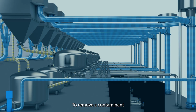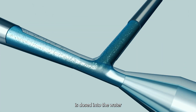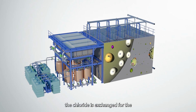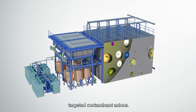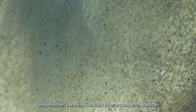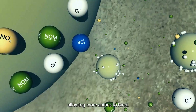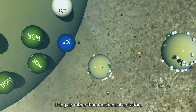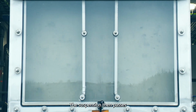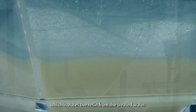To remove a contaminant like dissolved organic carbon, resin loaded with chloride ions is dosed into the water before it enters the 6 contactors. Inside, the chloride is exchanged for the targeted contaminant anions. An air system keeps the resin in suspension and refreshes the thin boundary layer around each particle, allowing more anions to bind. Using air rather than mechanical agitation keeps maintenance and energy demand low. The suspension then passes into a lamella separator, which isolates the resin from the treated water.